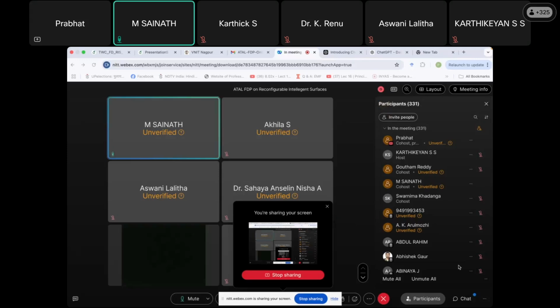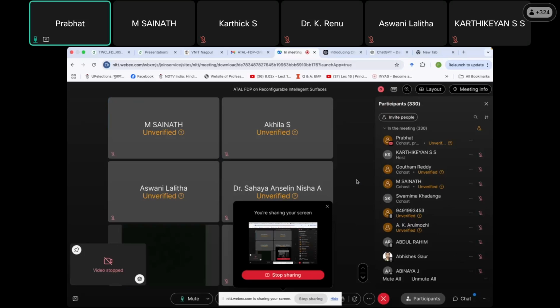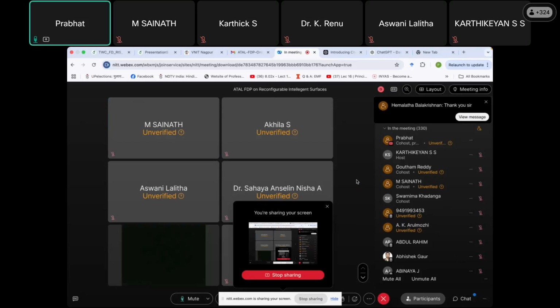Okay, sir. Moving to the next question. What are the key parameters to optimize when deploying RIS in a full duplex system? So when we are deploying RIS in a full duplex system, the key parameters are going to be the transmit power, because whatever power we are transmitting is going to come back at the receiver of the same node, right? And the reflections may also be coming back from the RIS, which is going to beamform to the same user. So the first parameter is power, then the phase matrix, and then of course the echo interference channel. When I'm saying RIS phase matrix, it includes both eta n and theta n. So I think these are the parameters.